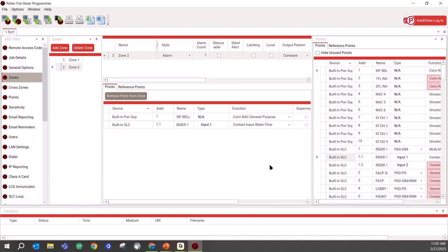I'm going to tell you why. Firefighters have a hard enough time decontaminating their turnout gear after a fire response. If you've ever seen a sprinkler system dump, it is most likely very dirty and smelly water. They don't want that dumping on all their turnout gear. So if they're going to turn it off, this also tells us, geographically speaking, where do I need to go to turn the sprinkler system off?